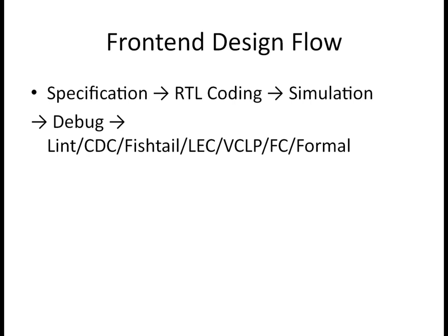In that case you are not assigning the complete signal to the output, so the tool will tell you this is a bit width mismatch issue, and your data will be lost. Those are actually flagged by lint. There are a lot of other rules that we can set as per our milestone.